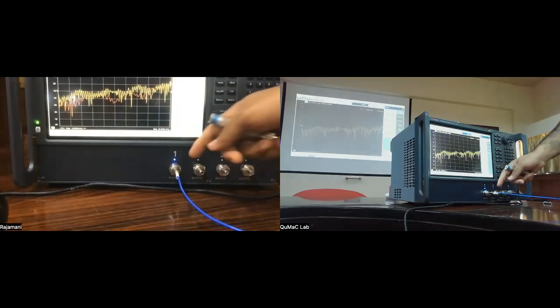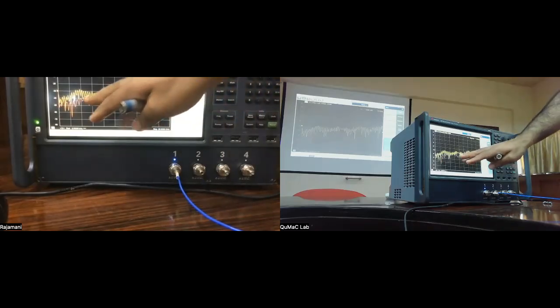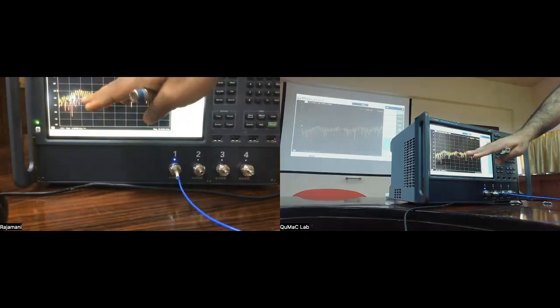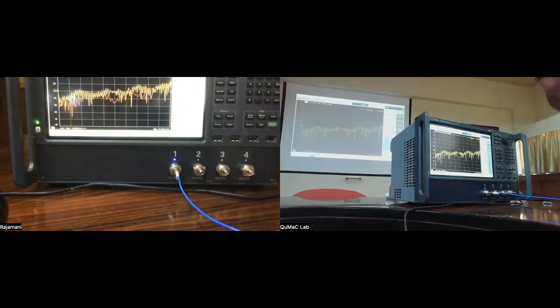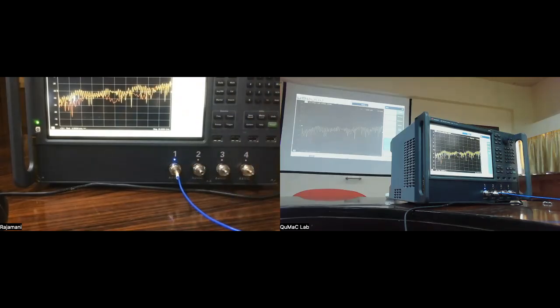So you see that once I connected the cable and put the 50 ohm on the other side, it's not the same as what we were seeing before, but you see there's an overall slightly degradation in performance. There's slightly more reflection. And that's probably because the cable's connector itself is a reflection point, or the cable's impedance might not be as close to 50 ohms as possible. Again, right now we are nitpicking mostly to understand these differences. This is perfectly fine as a cable.